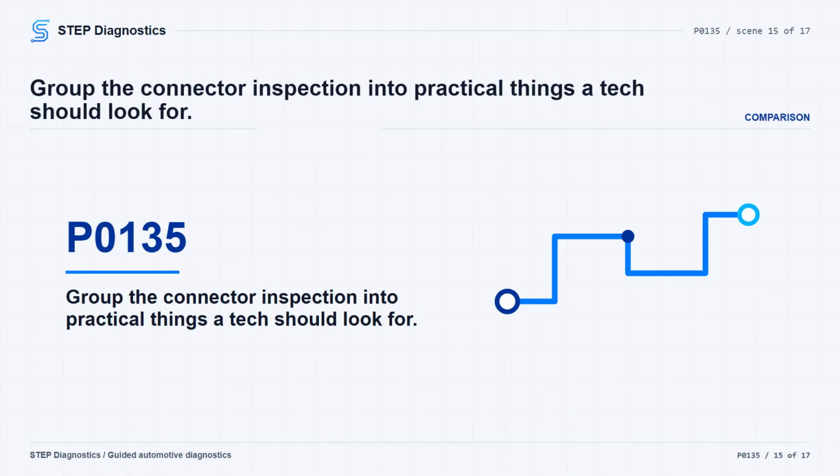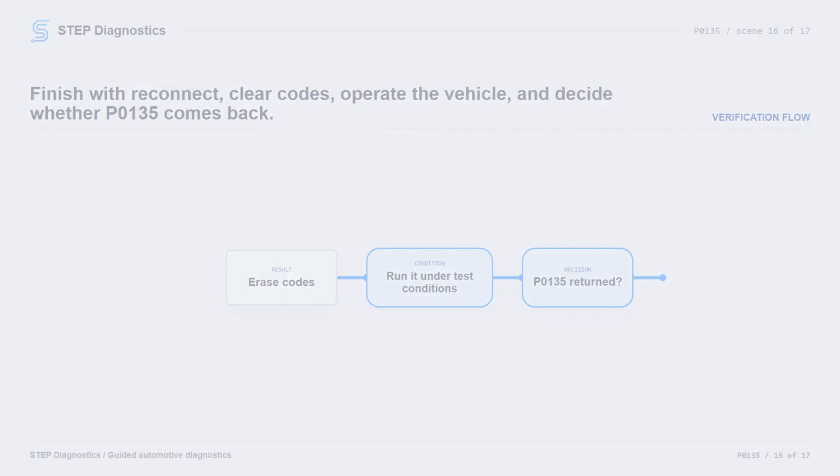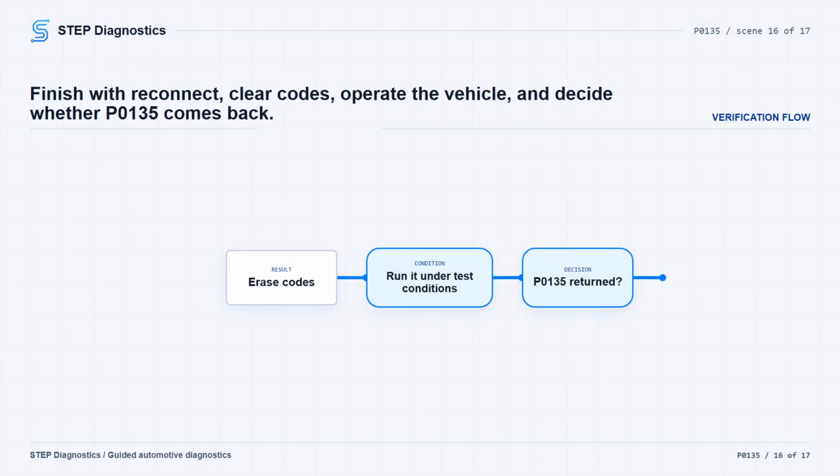If the sensor element, ground circuit, and heater control circuit all pass, inspect the related PCM inline and component connections. Disconnect the PCM connectors, any related inline connectors, and the related component connectors. Look for connector installation problems, damaged locks, corrosion, water intrusion, seal damage, bent terminals, overheated or discolored terminals from poor connection, push-back terminals, spread terminals, and poor terminal tension. Repair any conditions found. Then reconnect everything fully, making sure the connectors are seated and the locks are engaged.